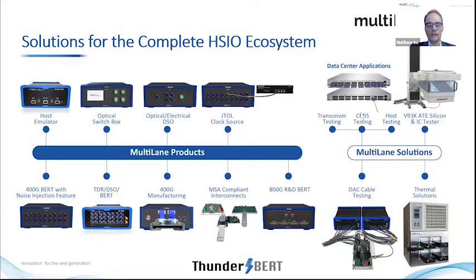We also provide high-speed test modules for the Advantest 93000 ATE tester, for testing ultra-high-speed ICs in an ATE environment. In addition, we also have a fully automated DAC cable test solution and thermal solutions to test transceivers over a wide range of temperatures.